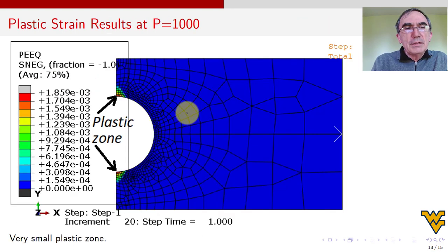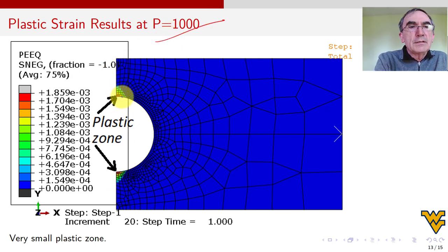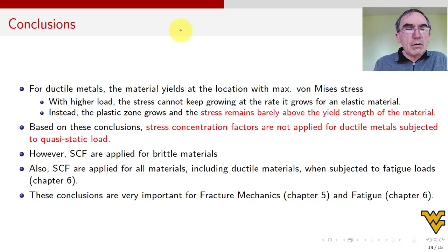But you see here the strain doesn't develop into a big area. It develops only on this, and here we are at 1,000. So the plastic strain, this blue is zero, that's there, it's zero. So that means there is no plastic strain. The whole thing is elastic. And if it is elastic, it's safe. And plastic is only this tiny bit, and I put 1,000, which is like 400 more than what it will take to start yielding. So the notch is totally blunted. It went away, okay?